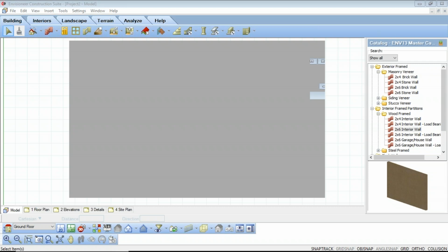if you want them to be on the same reports. The other variable would be when you're adding in your roof, the roof by perimeter tool will only work once on a location. So if I have a building and I add in that roof by perimeter and I have a separate detached building, the roof by perimeter will not work. I will have to use the roof by picking points option. So those would come into play as well.